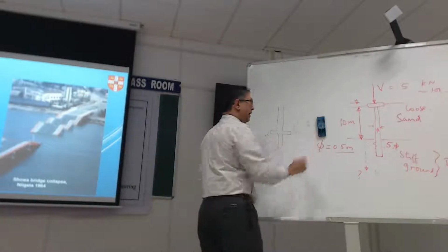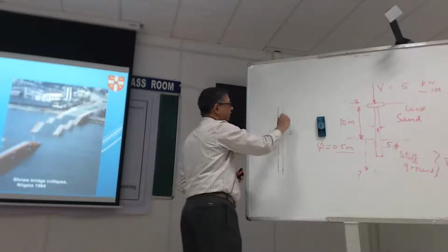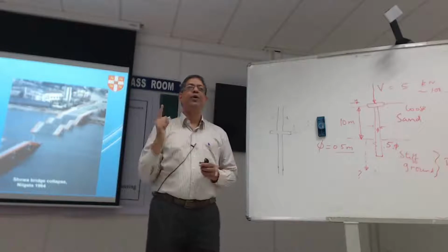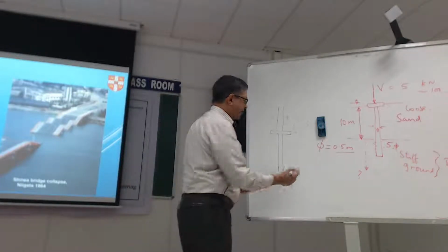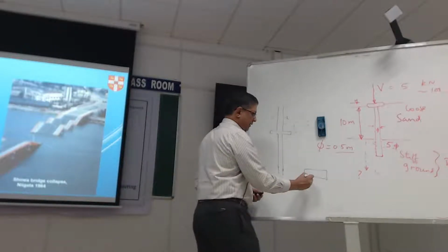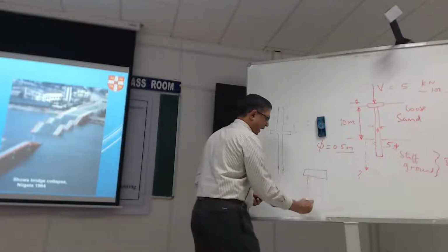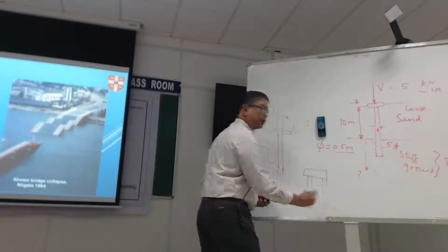So when it comes to this rotating, or falling, you've got only one pile effectively. With normal, modern bridge designs, you'd expect the deck, sorry, the bridge, the pile cap, and two or three piles, at least two.